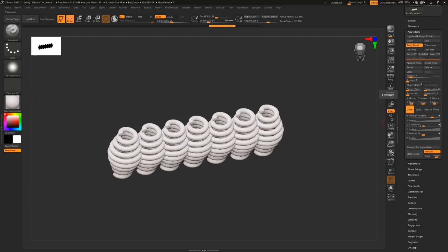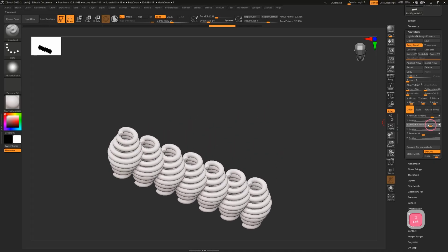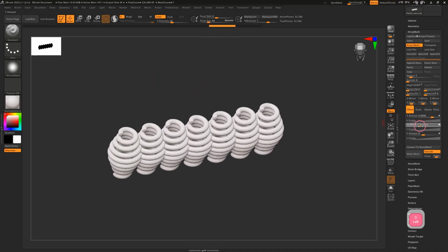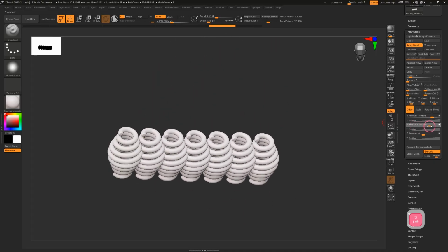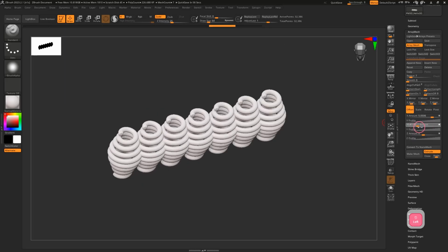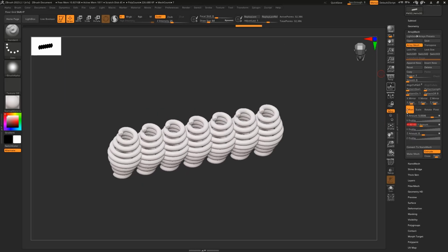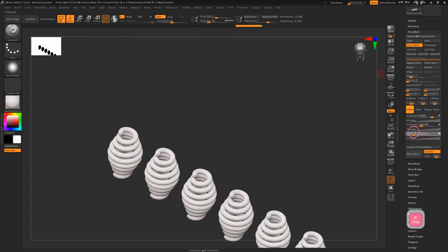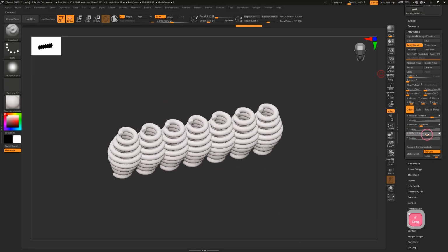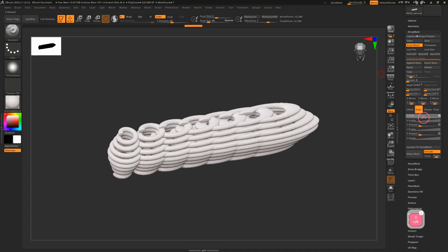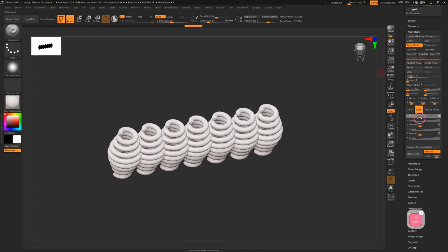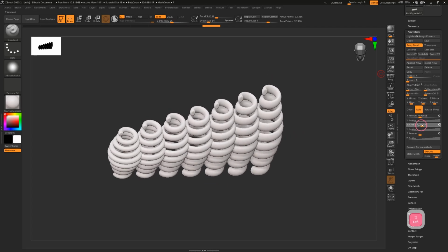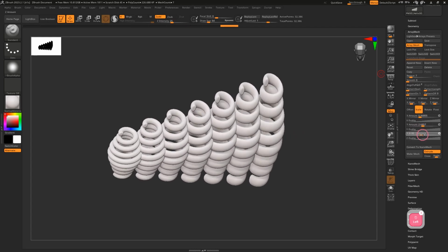And if you go to the Y amount, you can see that you're offsetting in the Y axis. And like I said last time, the Y is the Z in other programs. So be aware of that. And also the Z is basically the other side. It's pretty direct. The other one is the scale. If you click scale, you can see you can change the scale in the X-axis, Y-axis, and Z-axis.